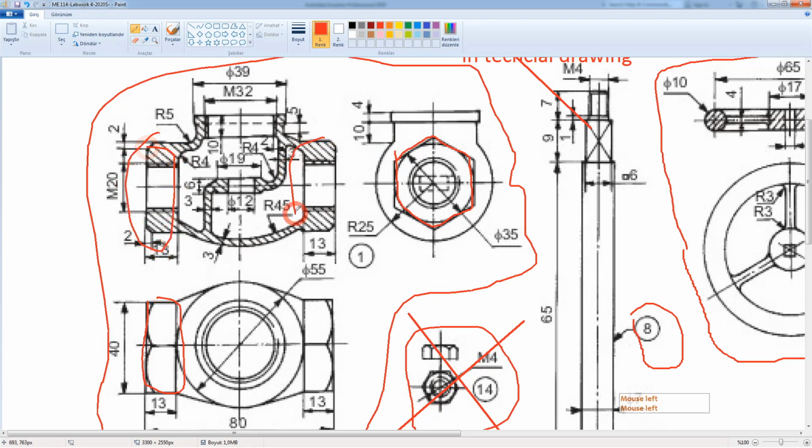After this one, I will create a body part by using some measures or path tools with the loft tool. Also, I will remove material with the revolve tool and add the inside feature here, which I'm going to make using the extrusion with two commands.